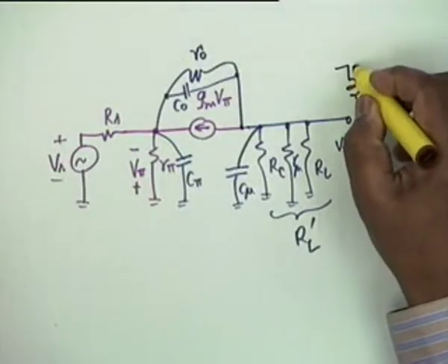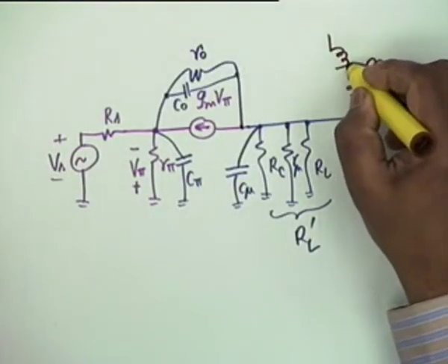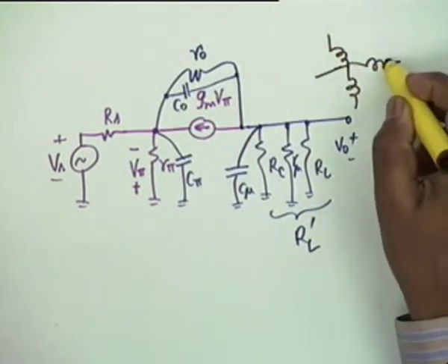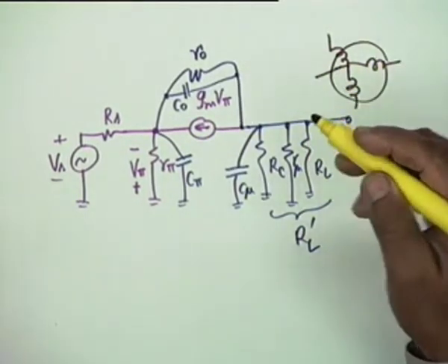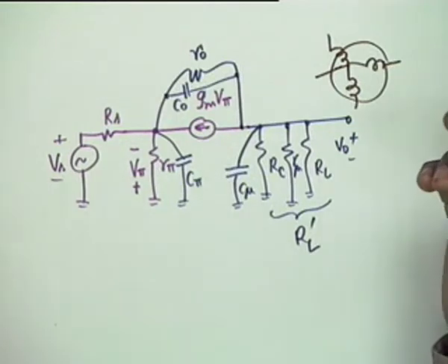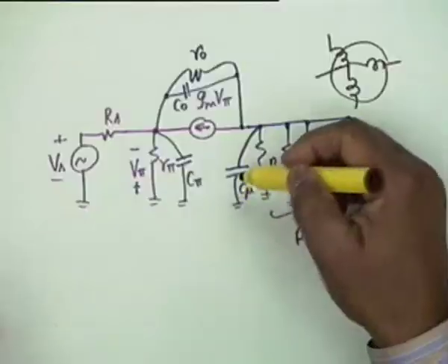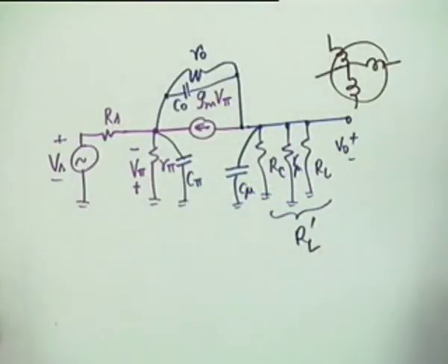Similarly, if you have a number of inductors connected at a common node, then the degrees of freedom is reduced by 1. If you have 3 inductors connected to a common node, the dynamics of the system will be governed by a second order differential equation, not a third order. Similarly here it would be a second order differential equation. So you have only 2 critical frequencies.